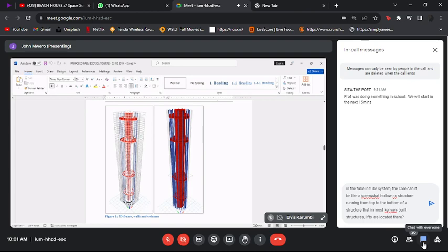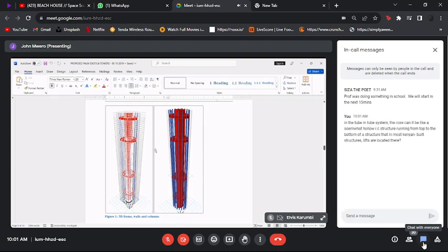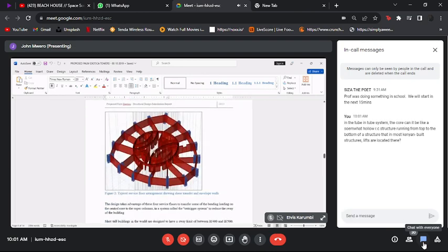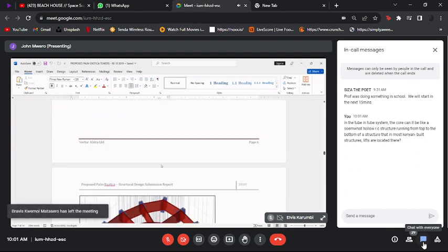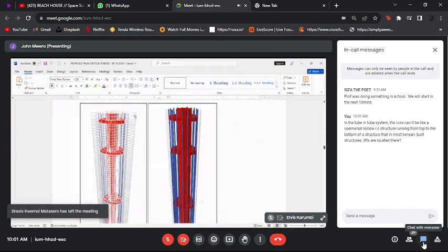So what I was showing you, this figure here is a blow up of one of those service floors where we put an outrigger system, and that's how it looks. So this building was a tube in tube. There were external columns, and then an internal core, and then I've shown you also the outrigger system.